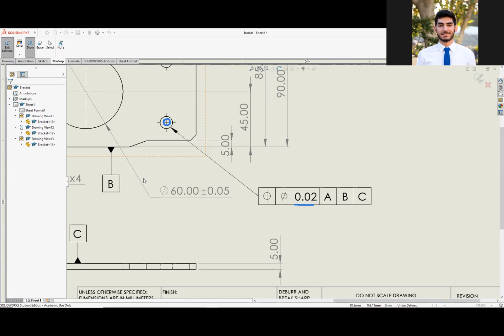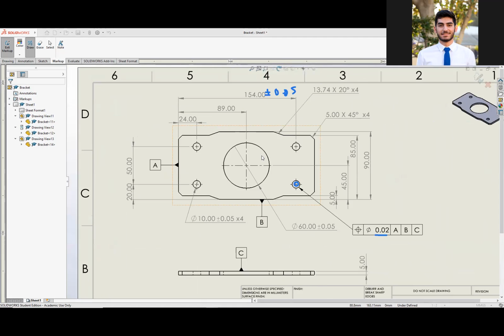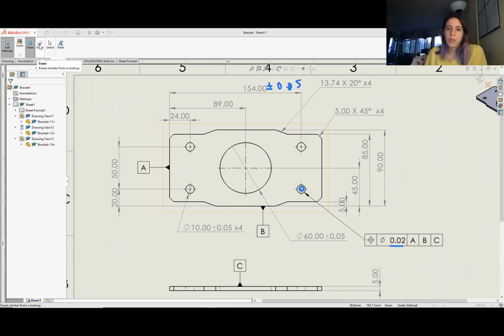Doesn't that contradict the square versus the circle? Just because one's 0.02 and one's 0.05, what's the significance of that 0.05 as soon as you take the circle and you say it has to be within this circle, which has a smaller tolerance?